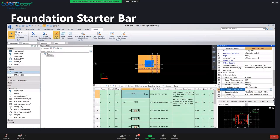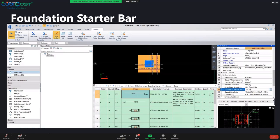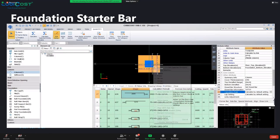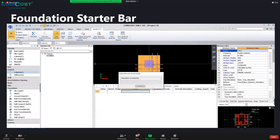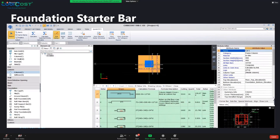So don't worry, I'm going to share with you all how you can adjust the bar type for your starter bar and how you're going to separate the quantity out. So as you can see here, I key in the bar type 16T10. Once I'm done, I calculate the column again, and observe closely on the edit rebar, 16T10. So with this function, you're able to adjust your bar type for your starter bar.